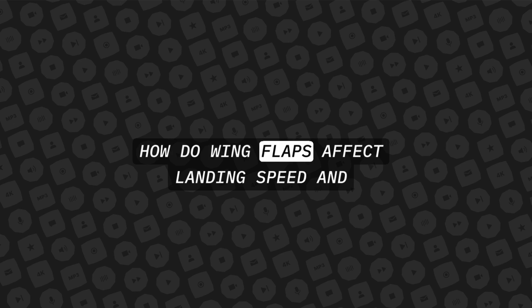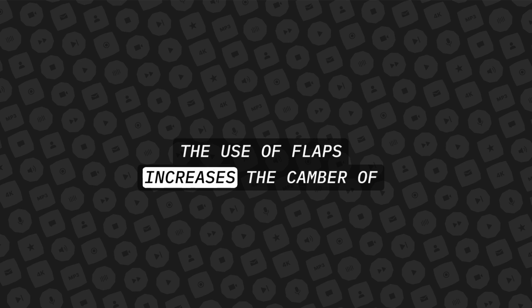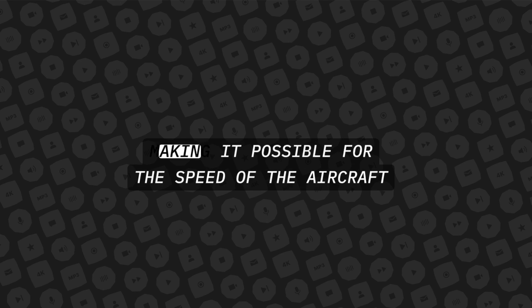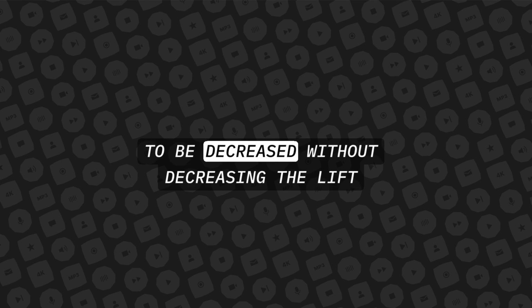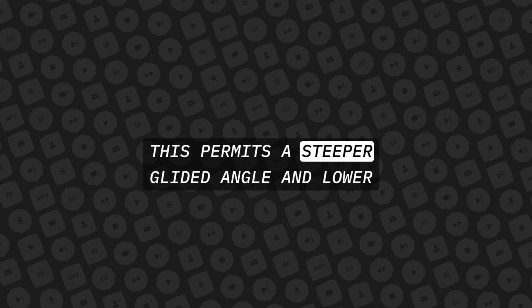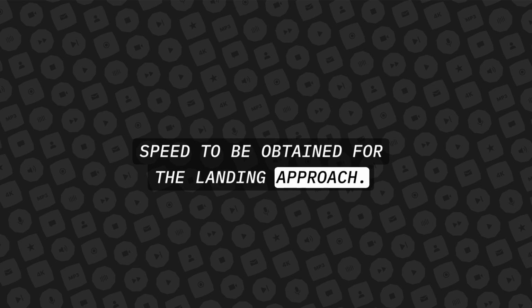How do wing flaps affect landing speed and approach angle of an aircraft? The use of flaps increases the camber of the wing and therefore the lift of the wing, making it possible for the speed of the aircraft to be decreased without decreasing the lift produced by the wing. This permits a steeper glide angle and lower speed to be obtained for the landing approach.